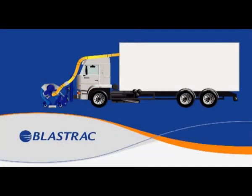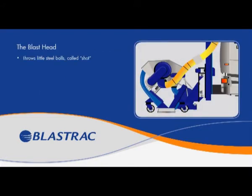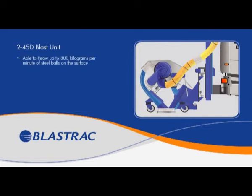In this animation, we briefly show you the working principle of the Blastrac truck with the 2-45D blast head in front and the efficiency of the new improved process of dust handling. The blast head throws little steel balls called shot with high velocity onto the surface to be treated. The steel balls simultaneously create both micro and macro structure on the surface. Skid resistance figures can be improved up to 100% compared to the value before shot blasting. The 2-45D blast unit is able to throw up to 800 kilograms per minute of these little steel balls onto the surface.